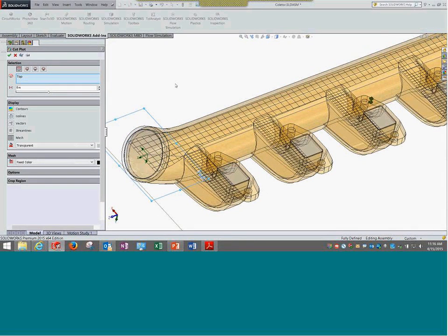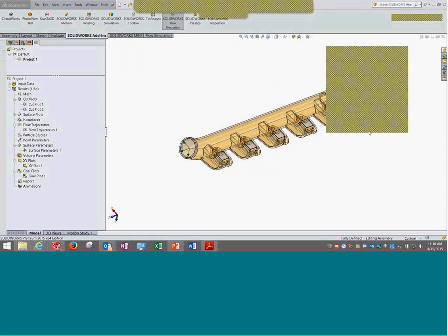And I think I saw some question coming in. Difference between results of surface parameters and surface goals. What is results of surface parameters and surface goal? It is absolutely the same, no difference. Surface goal, as I told you, will be used for convergence. It will ensure that convergence is happening. Whereas if at all, as I told you, you have not created any goals, then use this. That is volume parameters, surface parameters, and point parameters to see results at a certain point, etc. So if you forgot to create a certain goal, then you can use this.